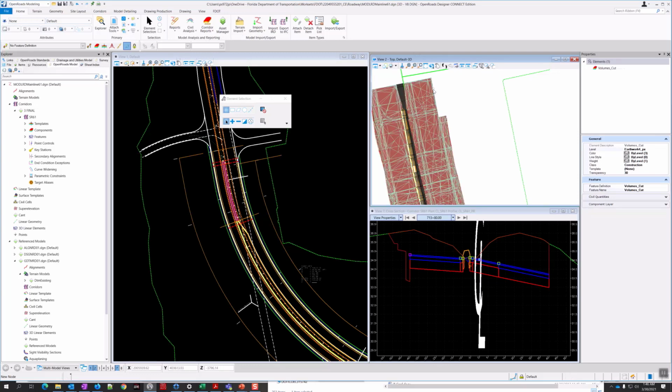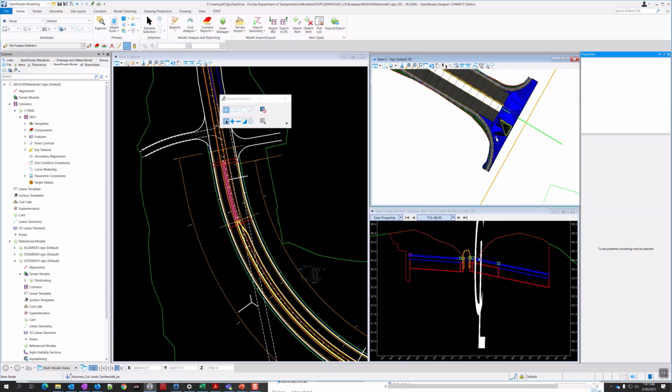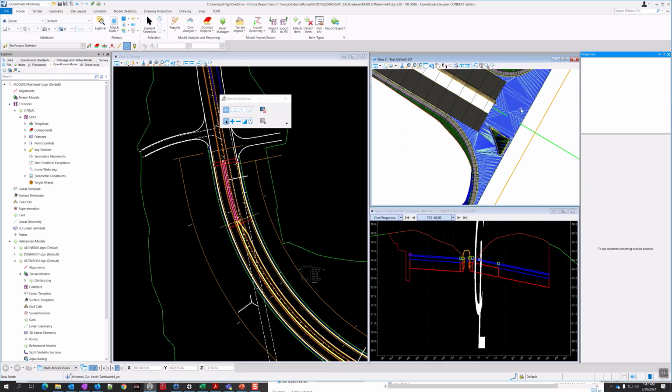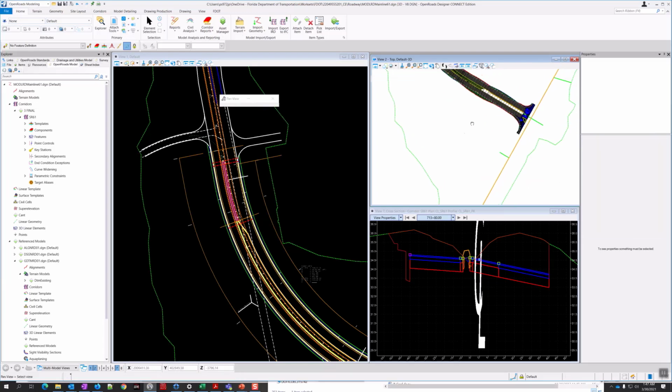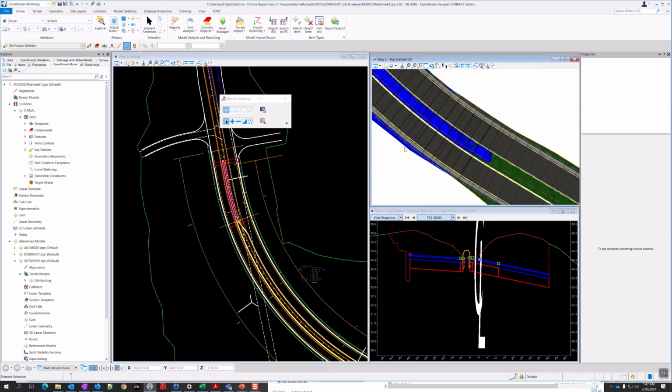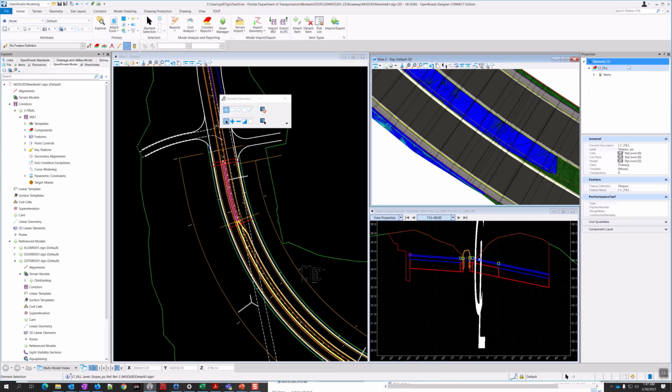Should be able to get the pop up. I can't get it to come up. So I'm going to right click over here in properties and do delete. So that got rid of one, and remember there's two shapes. Even if they're disconnected, you've got one for the cut, one for the fill. So we've got to find that fill. Okay, here it is. Look for the blue. So I'm going to select that.